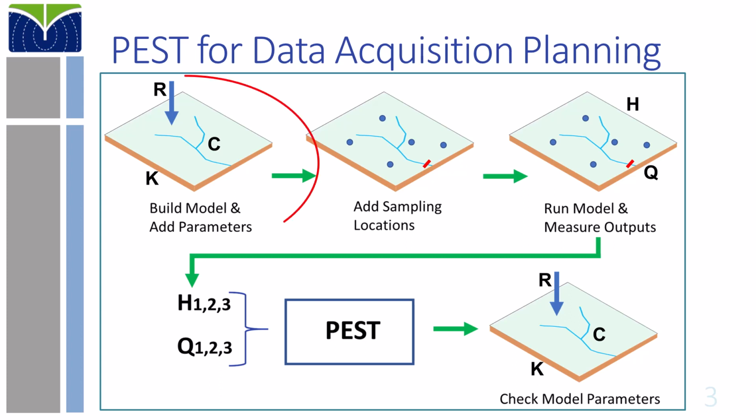Begin by roughing out a simple AEM groundwater model for your site based on your preliminary understanding of its conditions. In that model, place estimates of the parameter values that you will ultimately be using PEST to estimate for your model. For example, let's say recharge, hydraulic conductivity, and stream bed conductance. Add sampling locations in your model based on where and what type of data you plan on collecting at the site to characterize it.